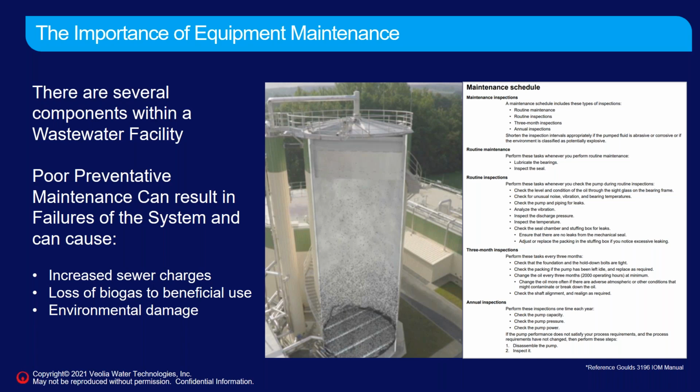So that's an example maintenance schedule for a standard centrifugal pump. We provide all the maintenance requirements for our equipment in our equipment manuals when we supply a new system. But it's important that operations and maintenance departments go through all that equipment and develop standard maintenance procedures and intervals so you can prevent unplanned outages and downtime of the equipment. Next.